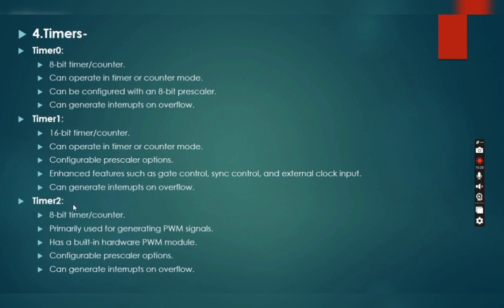Timer 2 has two count registers, TMR2 and PR2. The size of each register is 8 bit, in which we can write numbers from 0 to 255. The TMR2 register is readable and writable. PR2 is also a readable and writable register, and it is initialized to FFH upon reset. We have set PR2 equal to 250 in our code.